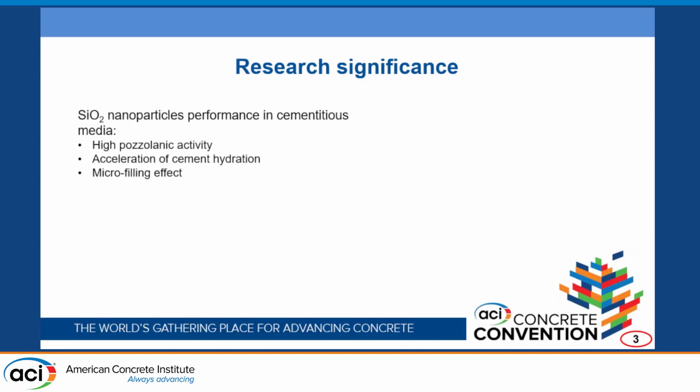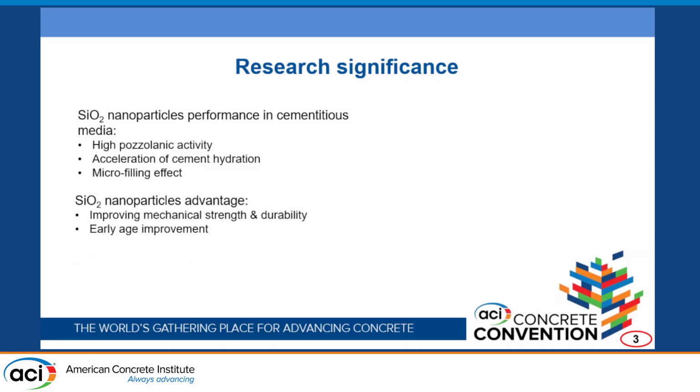Another thing that I'm going to talk about is the application of silicon nanoparticles. We know that they show different performances in cementitious media, including high pozzolanic reactivity, acceleration of cement hydration, and microfilling effect, among others. So using silicon nanoparticles has a couple of advantages.